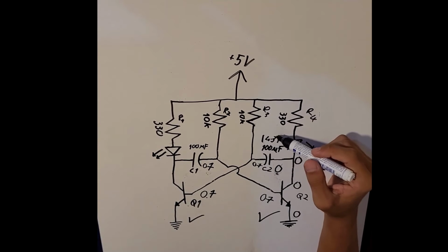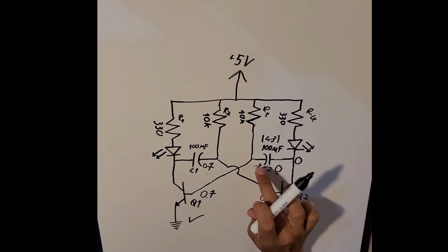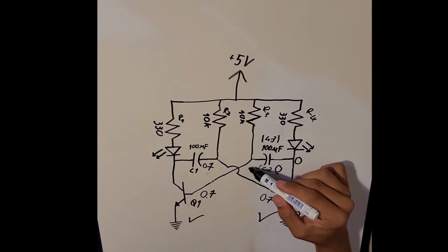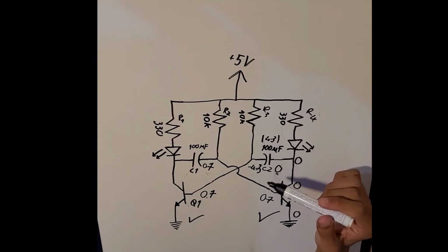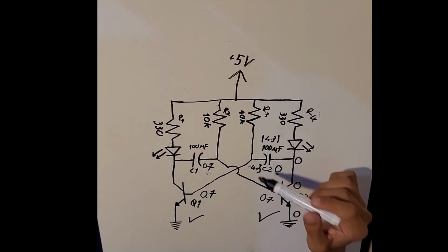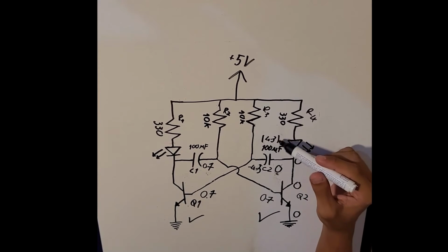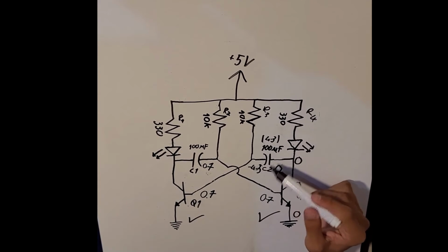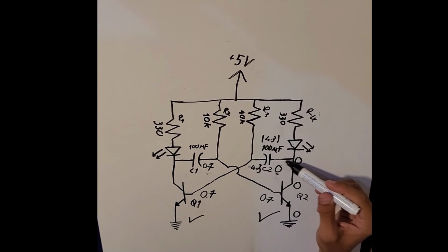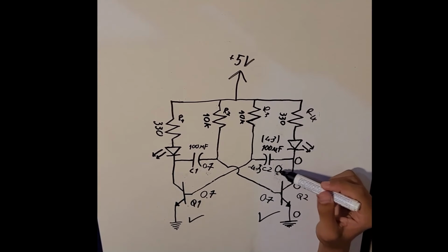C2 was fully charged and had 4.3 volts here, so we have 0 volts here. So we can say we will have negative 4.3 volts here. This might be complicated, but don't forget that voltage is actually a potential difference. We still have 4.3 volt difference between C2's two plates. So this side is connected to ground, so this is 0 volts, and this is 0 volts.